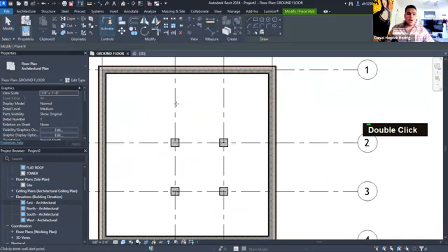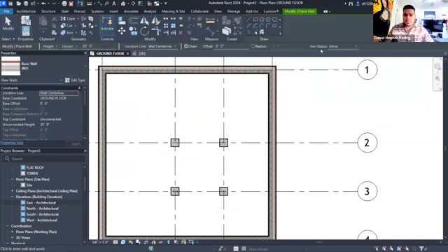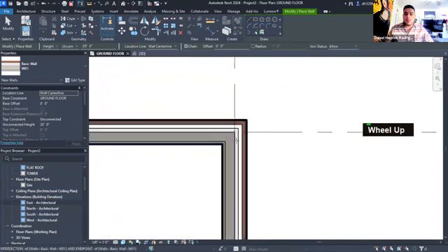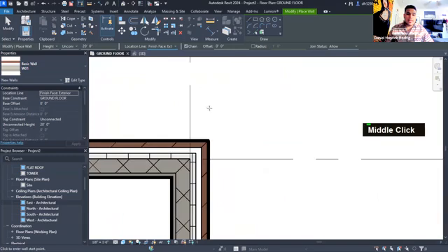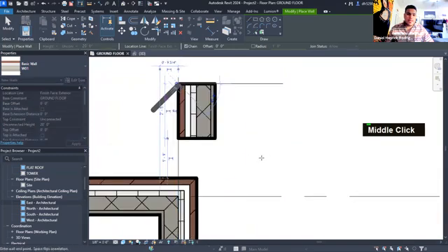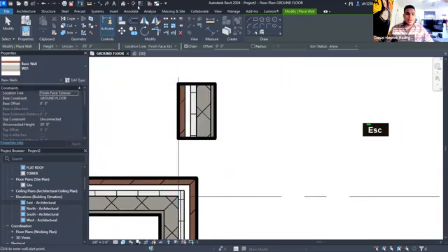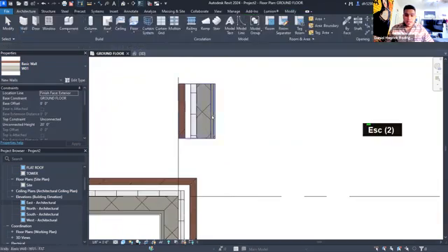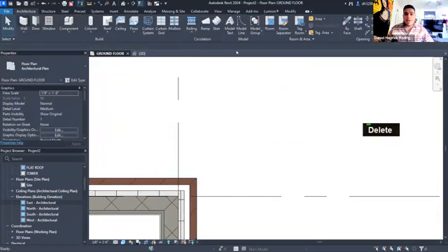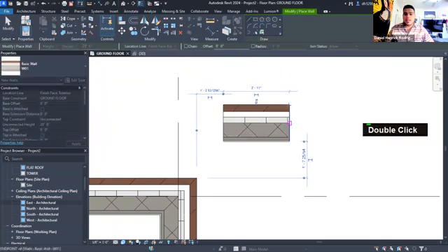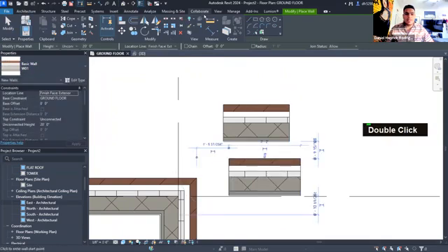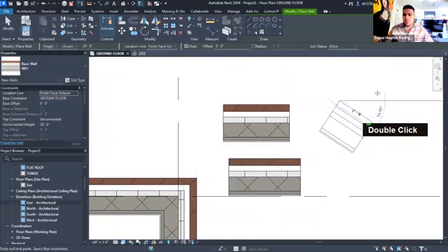Now, when you're placing down a wall, we have all this information over here. So it has the height, it has the location line. All these walls we place directly from the center on the grid lines, but you could put them from the exterior, and then you're going to have a wall where the exterior of it is on the grid lines instead. You have all these options. You also have a radius if you're doing a curved wall. You can unclick chain so that every time you click a wall, it doesn't stay together as opposed to this.